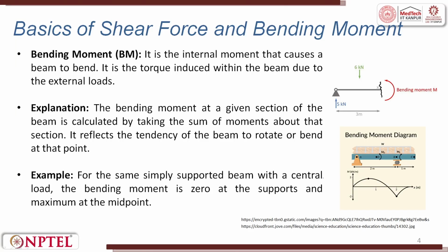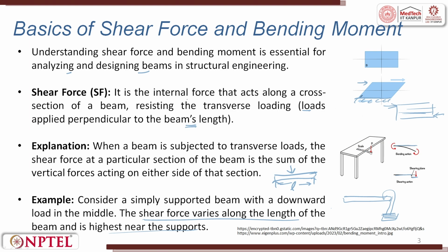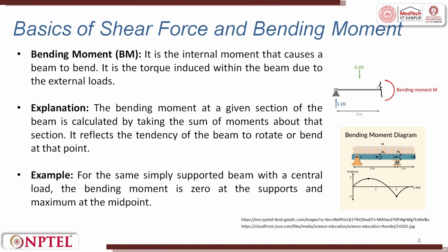Bending moment. It is also an internal moment. If you go to the previous case, we had shear force, also an internal force acting along the cross section of the beam. When we do bending moment, it is the internal moment that causes a beam to bend.